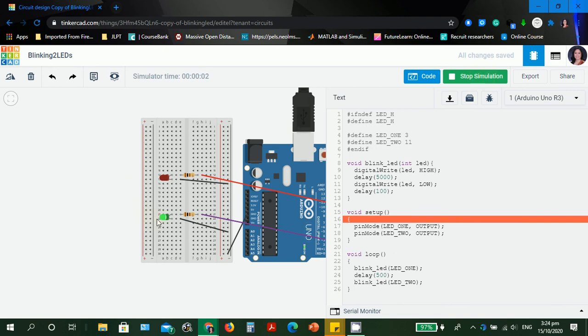You'll count up to 5. Okay, then half a second. Then again, another 5. Okay. So the status high has longer duration than low, and then we make the delay shorter between the two LEDs. So again, before you edit, you must stop the simulation.